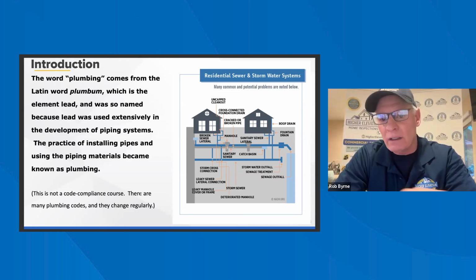When you're looking at water supplies, one thing to understand is that most leaks occur where the threads are cut into the pipe, because as you look at this picture, you can see when you're threading a pipe how it cuts into the thickness and the diameter of the pipe. So a lot of times with galvanized supply lines, you'll see corrosion or leaks, usually at this point. Sometimes there's a defect in a pipe and it'll leak elsewhere. Also, if there are dissimilar metals, like a steel pipe with copper straps, it's going to corrode. Be on the lookout for that.